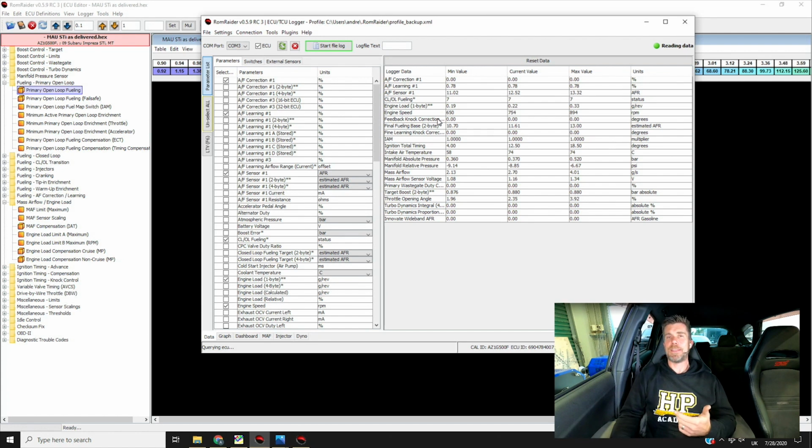So there's another parameter in there, and I know this starts to sound complex, which is the IAM, or ignition advance multiplier, also often referred to in other software such as COBB as DAM, or dynamic advance multiplier. So how that works is we've got our base timing, essentially the minimum timing the engine will run. Then we've got our advanced map, which is the maximum additional advance the ECU can add. So it takes our maximum advance value, our ignition advance adder, and multiplies that by the ignition advance multiplier, which is a number between 0 and 1.